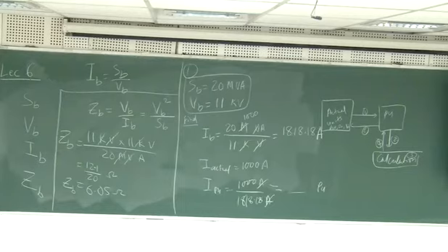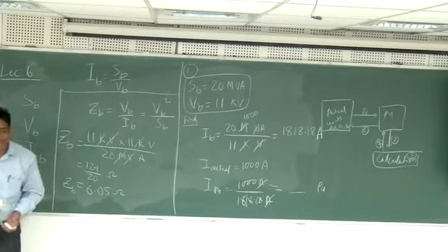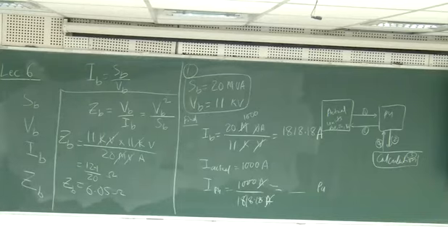So you can always, just for the calculation sake, say I want I base as 100 amperes and then I want Z base as 5 ohms. Then what are the other two? So you can do all those calculations yourself, so I'm not going into those details. All right. So just now what I discussed is choosing the per unit system for one electrical problem.